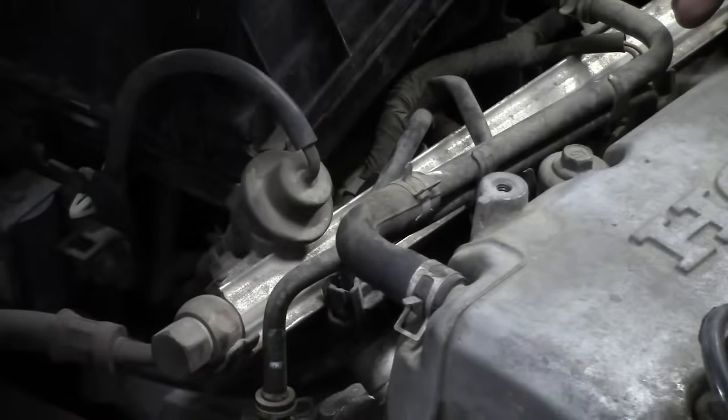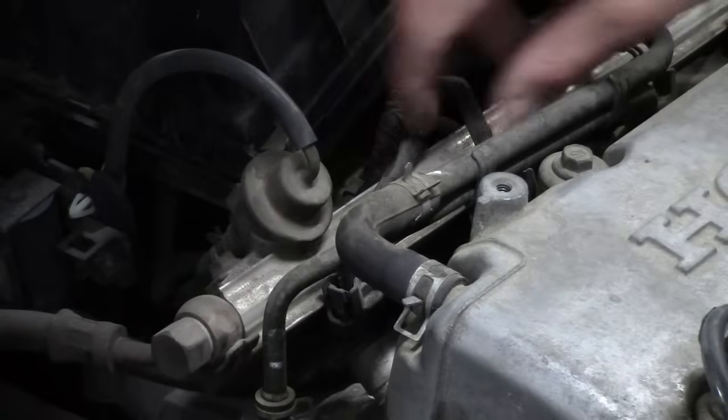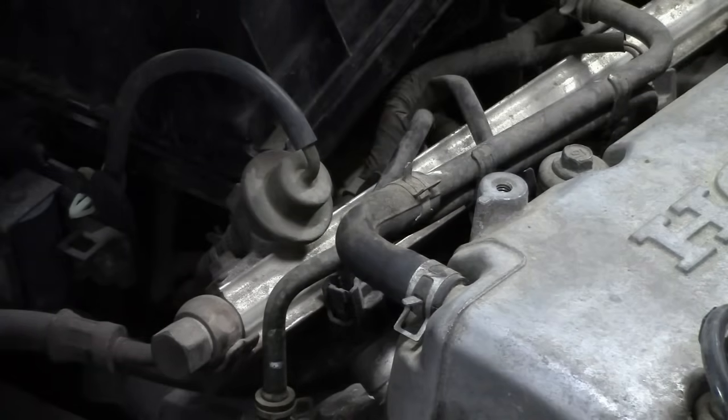One thing I do want to do is a couple things. First of all, I have my scan tool here. So I am thinking we can just hook up the scan tool, and I will bet you there is going to be a cam or a crankshaft position sensor error code. The other thing I want to do, just for my own confirmation, is really definitively confirm that we have no signal to the fuel injectors. And there is an easy way that I can do that just looking at the wiring.